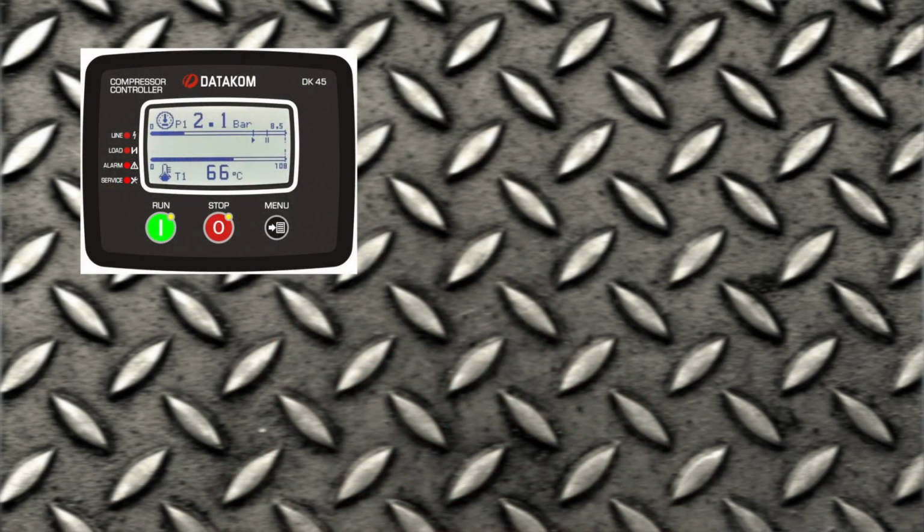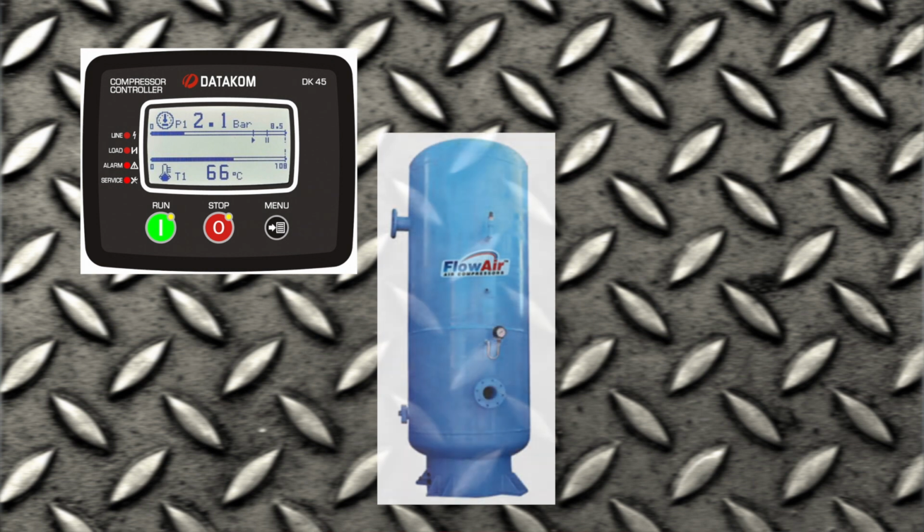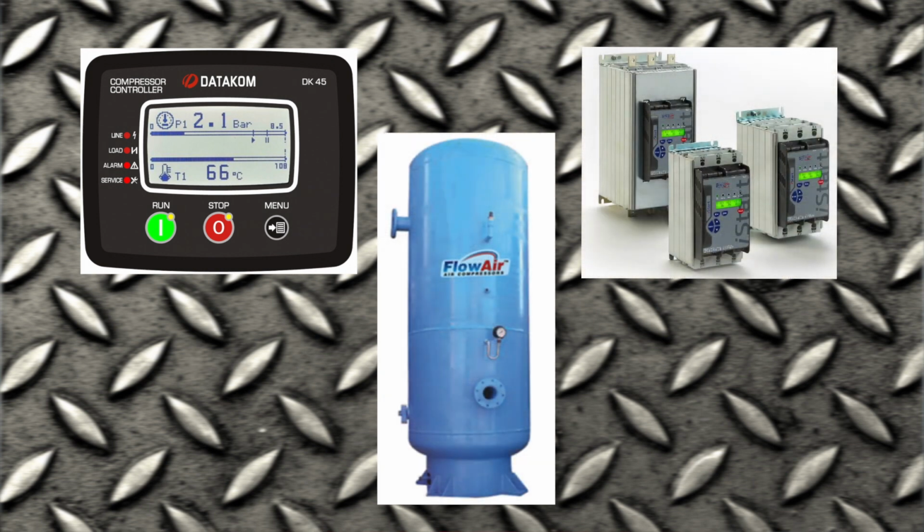Finally, when you're all done with your hardware analysis, you can look and see what kind of control schemes you can use to improve things. Can you run your recips as on-off? Maybe by putting in an extra receiver tank. Can you upgrade to variable speed drives? Or probably, more commonly, when you add an additional compressor, can I make that one have a variable speed drive so that I can match my load to what the system needs?